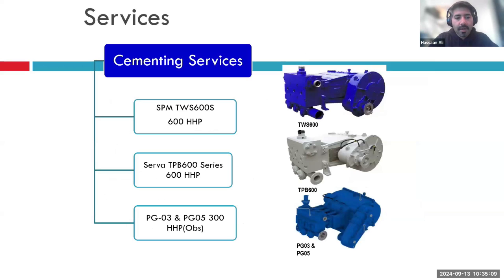We were talking about different types of pumps. The cementing pumps, you can see right over here, are smaller pumps compared to stimulation pumps. Usually these are triplexes, not always, but most of the time in the cementing unit what you will see is a triplex kind of pump. You can see the gear reducer right over here mounted at a 45-degree angle. One of the ones which you will see right over here is a particular model of pump with a chain drive rather than a gear reducer.